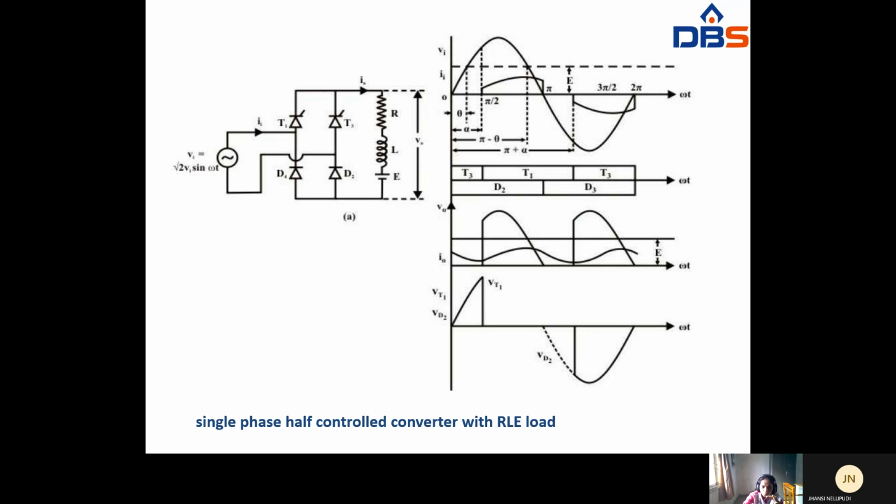And the output voltage, when the thyristor is triggered at alpha, the output voltage becomes, and it becomes 0 at pi minus alpha. Again it will be increasing at pi plus alpha. So this is VD1, and this is the input voltage. So the diode voltage VD1 will be like this.